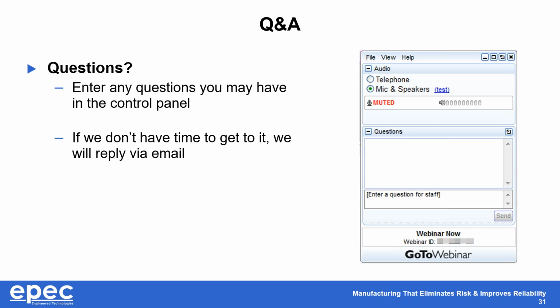Third question that we're going to cover refers to material lead time if a design requires a non-standard stock material that we covered earlier. Lead times on materials will vary depending upon the volume and the manufacturing location. I think it's fair to add at least 2 to 4 weeks for non-standard stock materials, and that's provided that it is a standard manufactured configuration. If it is now a unique custom, the lead time on materials can easily grow into the 4 to 8 week range.